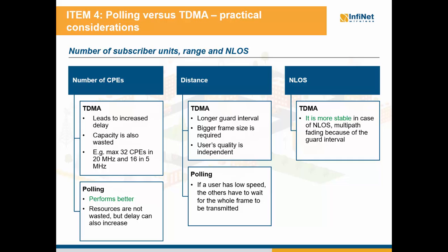The fixed transmission intervals and the guard interval make it easy to determine the useful signal and wait until the multipath components vanish before switching between the RX and TX.